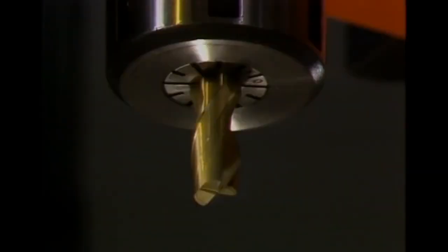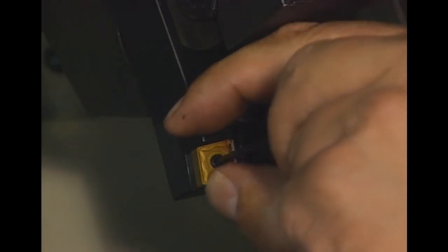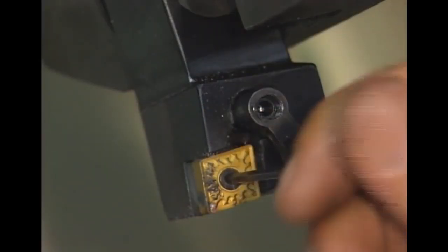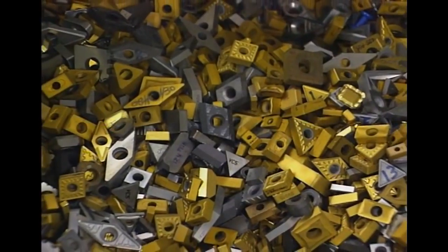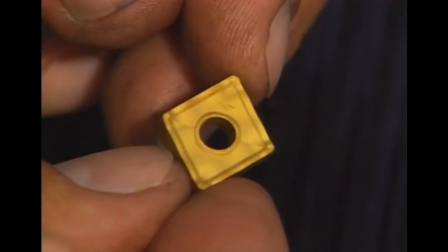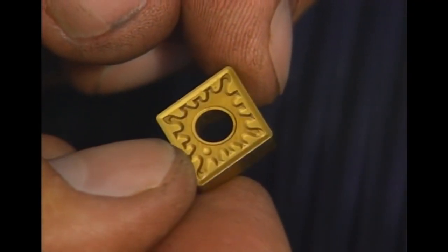Carbide is utilized for solid round tools, such as end mills and drills, or in the form of inserts clamped to a shank or holder. Inserts may be indexed to another position when an edge has worn. When all the tool edges on an insert are dull, the insert is generally thrown away or recycled. Some inserts are single-sided, others double-sided.